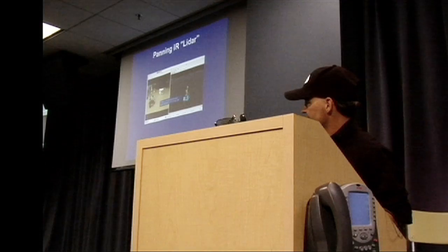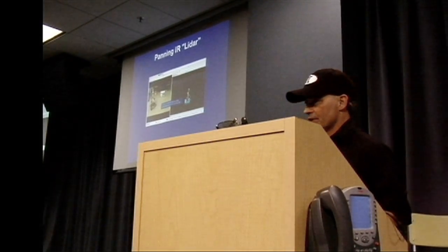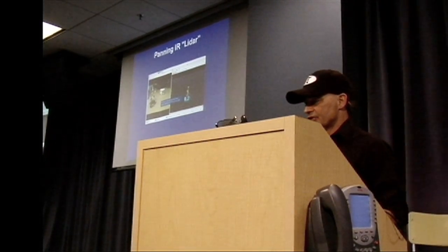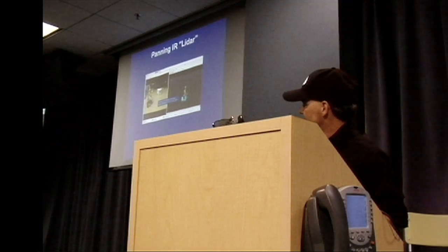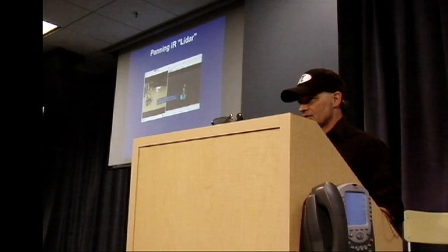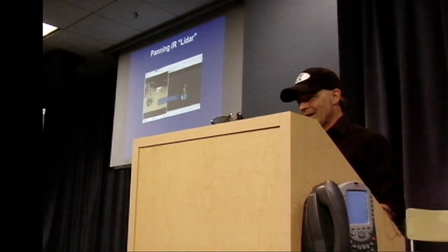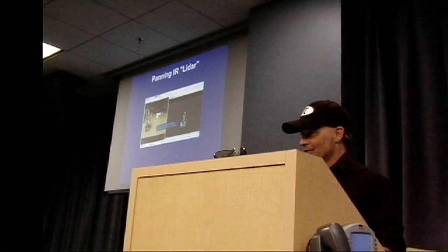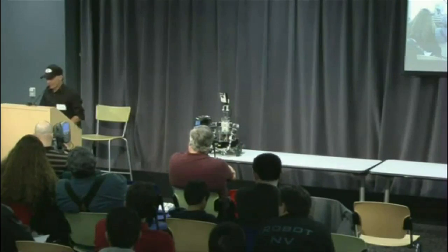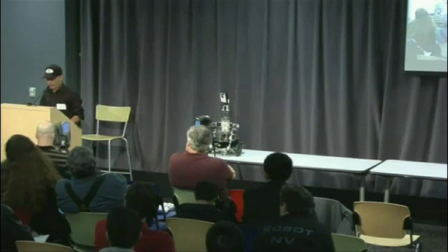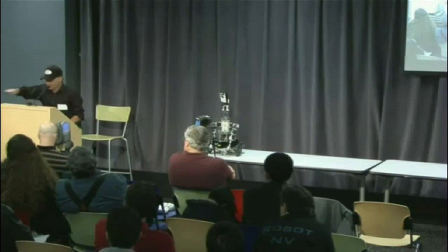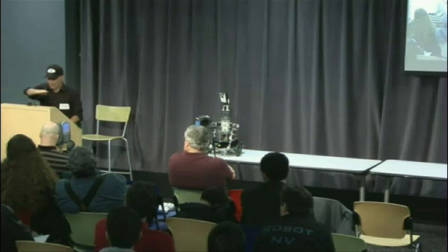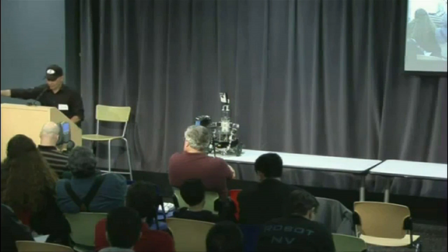Before we look at a couple of things higher up, like SLAM, just in terms of some demonstration videos, I wanted to show you this one thing, because this is much more appropriate to the hobbyist level. If you don't happen to have a laser scanner, which tends to be fairly expensive, although now with the Kinect, there's the possibility, of course, of doing SLAM visually using essentially a slice of that 3D vision map as a pseudo laser scanner.